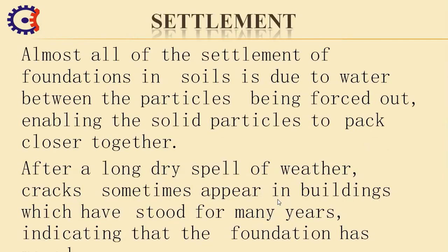So the next is settlement. Settlement is also an important part because the soil has a moisture content. Almost all the settlement of foundations in soil is due to the water between the particles being forced out, enabling the solid particles to pack closer together. After a long dry spell of weather, cracks sometimes appear in buildings which have stood for many years.